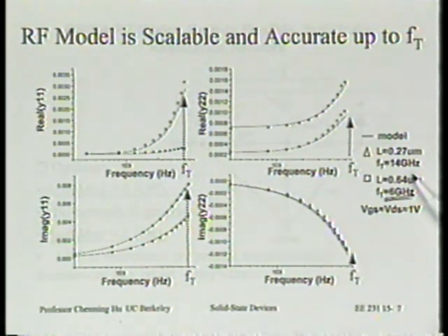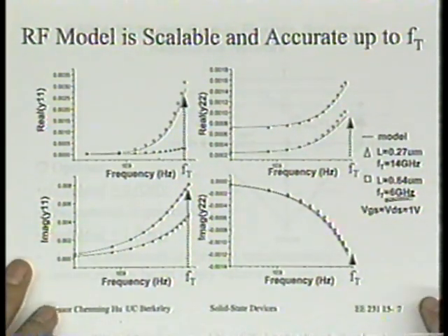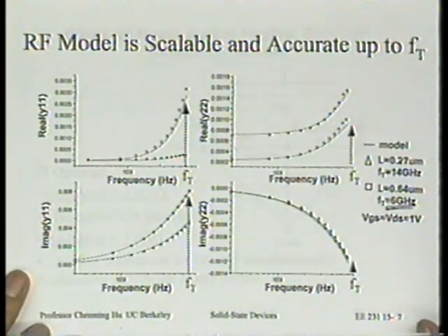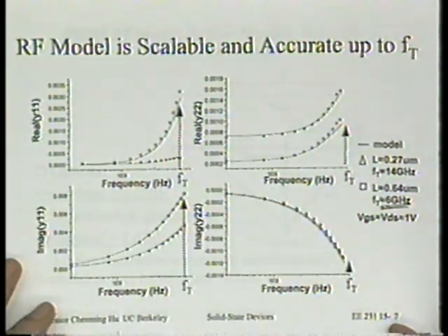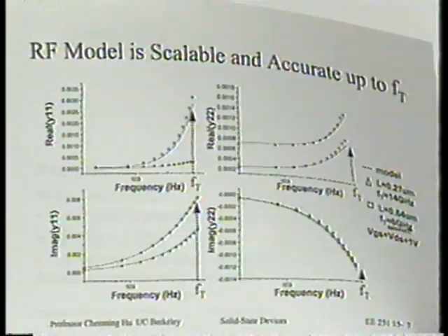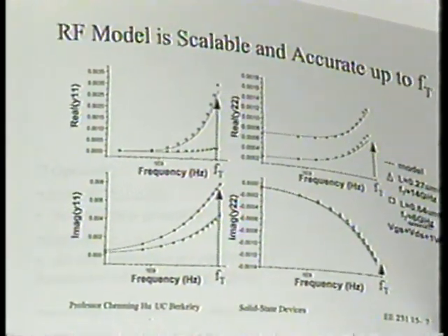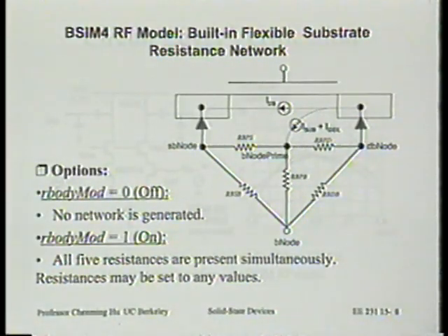So you can see this simple addition to the transistor immediately made the transistor accurate all the way to close to FT. But you have to be able to model the transistor value correctly, model its VGS dependence, L dependence.